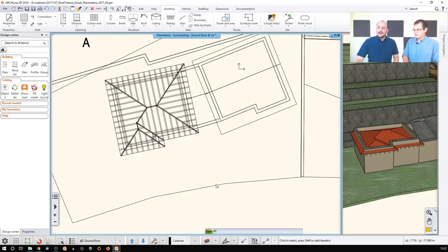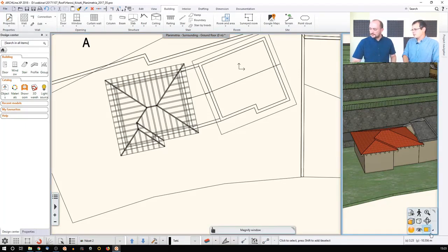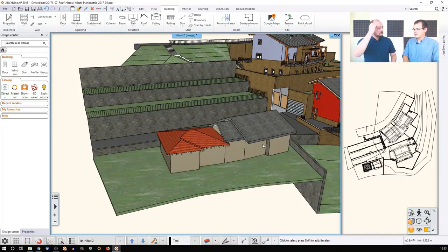You click here, and then you update the model with the current settings, and then the miracle happens when the walls are cut by the roof, because now the software is considering all connections between the structure, and once it's done, as you can see, it's disappearing now. That's right. So this way you have a direct command on when you want to update the 3D model, and that conserves some processing power from your computer.